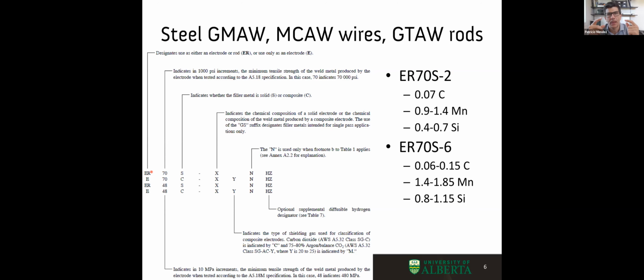So when I'm doing MIG, I'm pulling the wire, that's my electrode. But when I'm doing TIG, that exact same wire can be cut into lengths of rods. And those are not electrodes because they don't conduct electricity, but those are the ones I feed into the weld pool. So when it's solid material, it is ER, electrode or rod, and it's followed by a number.